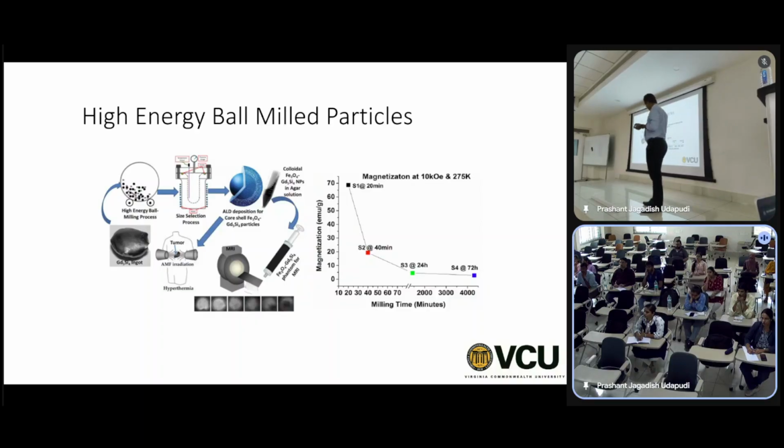Once you do the annealing, you do the ball milling. So you have ball milling here. This is the material, the powder that you get, and you can use this powder for additive manufacturing. In here, we further size selected it. Actually, if you have this wide distribution of particles, sometimes it's helpful in some additive manufacturing techniques, sometimes it's not.